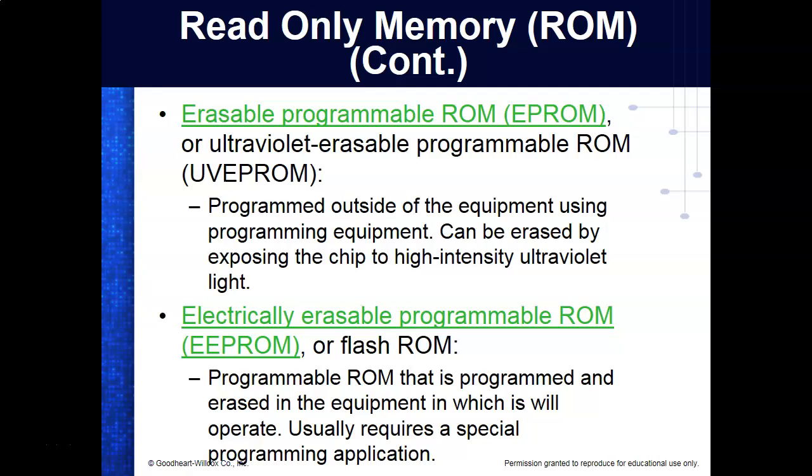Erasable programmable read-only memory. I can show y'all these when y'all come in. These are glass. You can actually look in and see the actual wafer in there, or the chip. You can't see the transistors, but I've got that magnifying glass that we used to look at the triads on the screen. We'll look inside an EPROM. We could reprogram these, but we had to erase them with ultraviolet light. It was a real high intensity, so you had to be careful. It was all sealed up, and we'd put them on some anti-static foam and put it under there, and it would erase them in about 30 minutes.